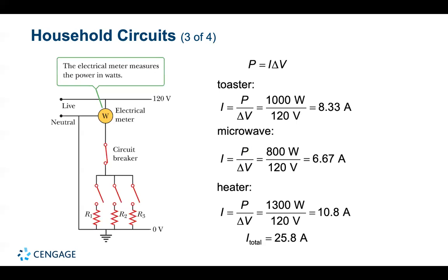When wiring, both the wire and circuit breaker are carefully selected to meet the current demands of a circuit. If the circuit is to carry a current as large as 30 amps, a heavy-duty wire and an appropriate circuit breaker must be used. Household circuits that are normally used to power lamps and small appliances often require only 20 amps. Each circuit has its own circuit breaker to accommodate its maximum safe load.